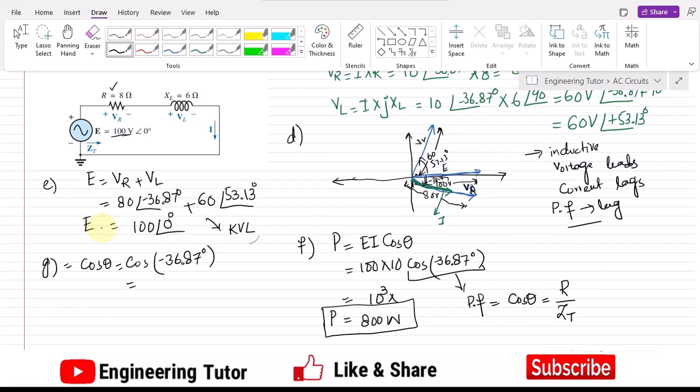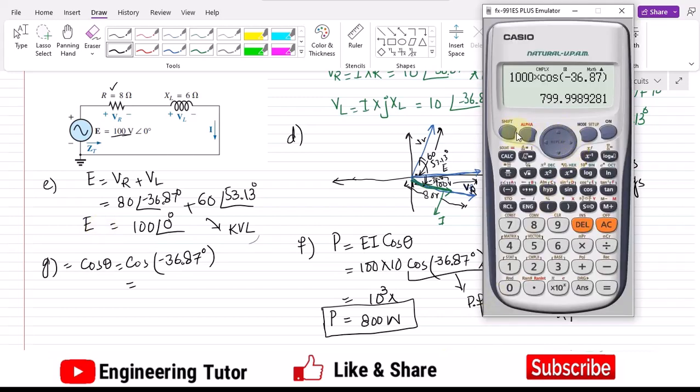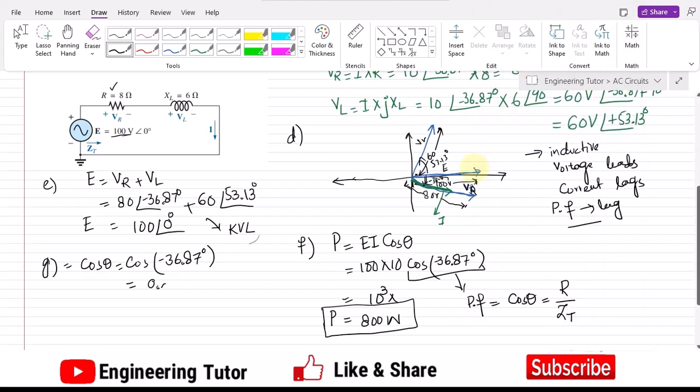Okay, so let me calculate it. Cos of minus 36.87, so how much is it? That is almost 0.8. Okay, as the circuit we have is inductive, and I have told you that in any inductive circuit the current lags, therefore this power factor is lagging power factor.